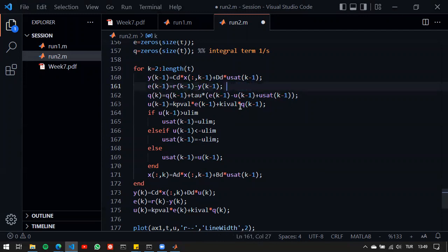So, of course, it raises a question here because we have K minus 1 here. We need the control signal K minus 1, but we are calculating it here, down here. So we don't actually know the value at this point. Instead of doing this for K minus 1, we might just have a certain delay here, just one sample. And instead of doing this, we might go ahead and look for the previous control signal that was applied and the previous saturation value that was applied.